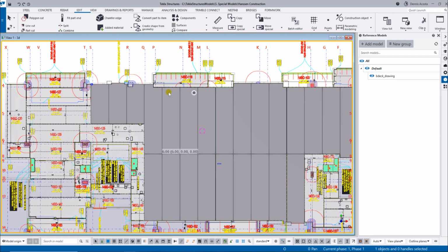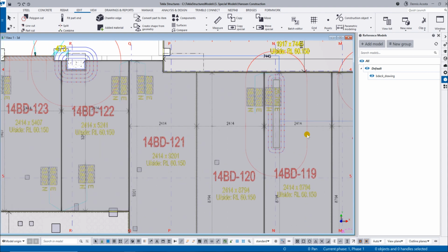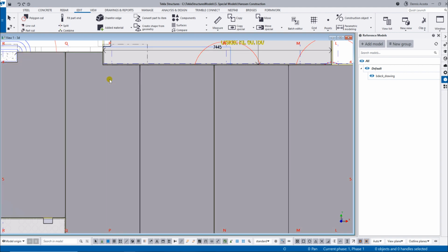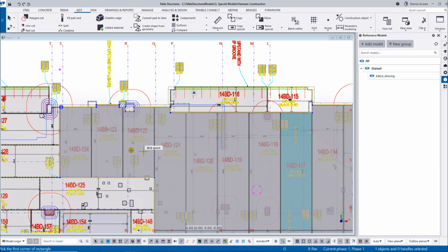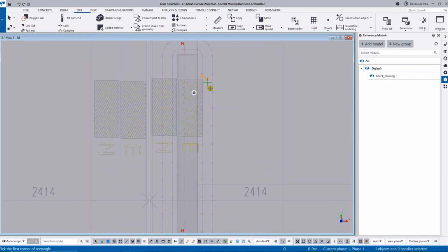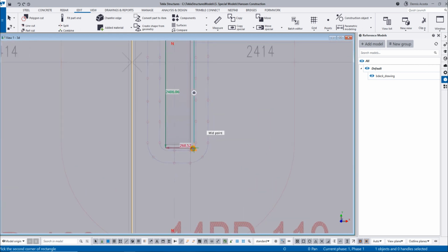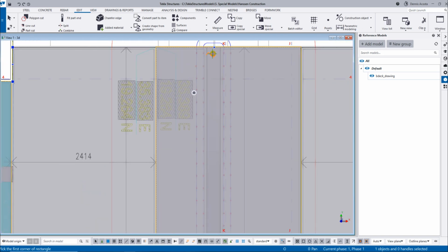Okay, so with this floor layout tool, again, just to show you how we can add the opening here, just control. So from here, I can just simply select again the direct modification and then select the slab. Okay, and then from here, I can use this opening, this one, add new rectangular opening. So if I may select, okay, where is that one? Maybe this. Okay, that one. Another one here.